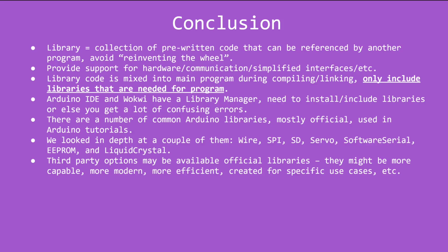A reminder about the limited resources of things like the Arduino Uno Rev 3. The Arduino IDE has a library manager. You'll need to install libraries or else you'll get a lot of confusing errors. There are a lot of common Arduino libraries, mostly official, used in tutorials.